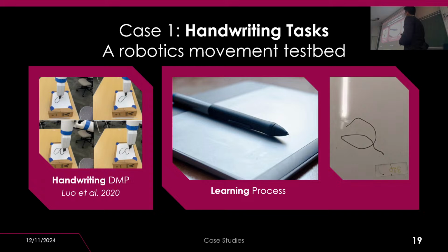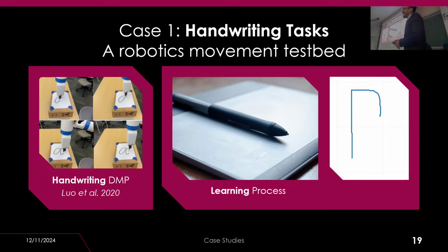What if we wanted to learn perhaps something more difficult like uppercase B? It may not seem that difficult. However, the initial value and the goal value being too close, so basically it being a closed grapheme, represents an issue for classic DMP. Not only that, but what if we wanted to rotate the shape, the grapheme, as to write it over a different plane of work, a workspace, a workbench, as well as scale it since the workbench is of different size?